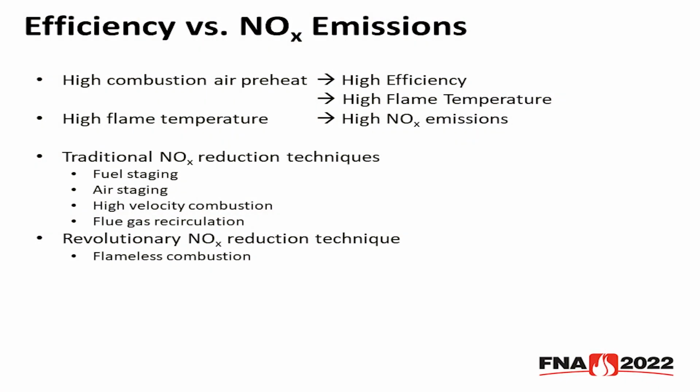Okay, so as I said, these techniques have been around for quite a while. They're fairly effective, but today NOx emissions requirements are more stringent than ever. Plus, new burner technology with higher combustion air preheat makes it more of a challenge to keep NOx under control. Fortunately, there is another technology. I'm not going to call it a new technology. It's been around for a number of years, but it is revolutionary because it brings NOx down to extremely low numbers, and that is known as flameless combustion.